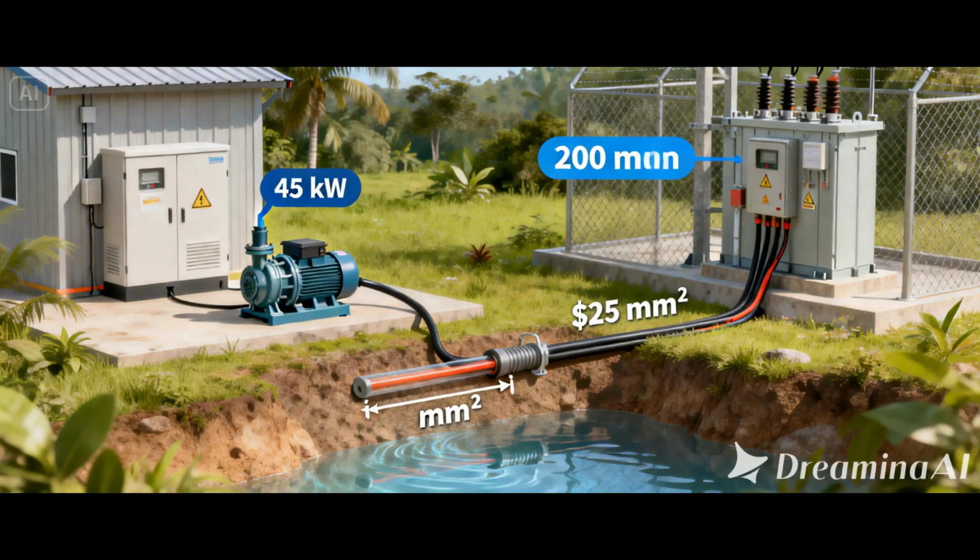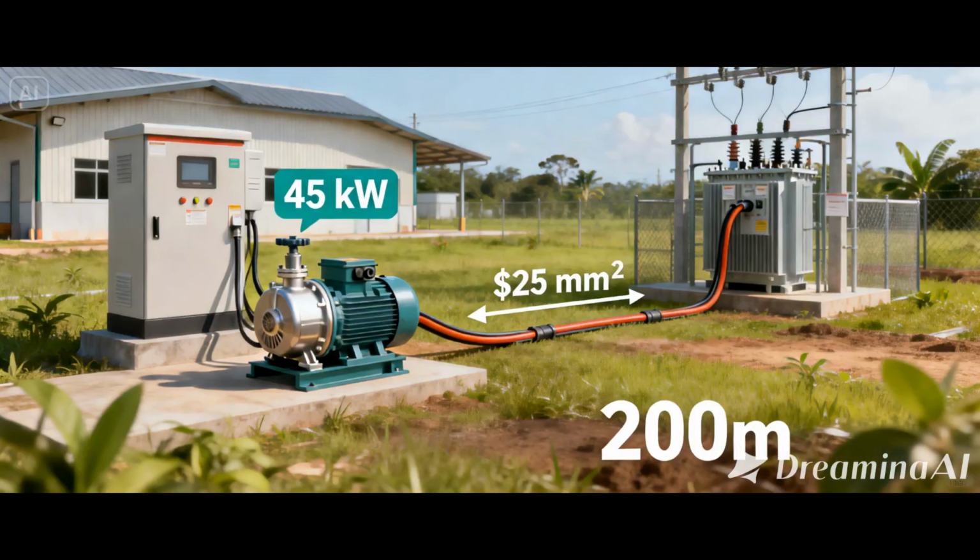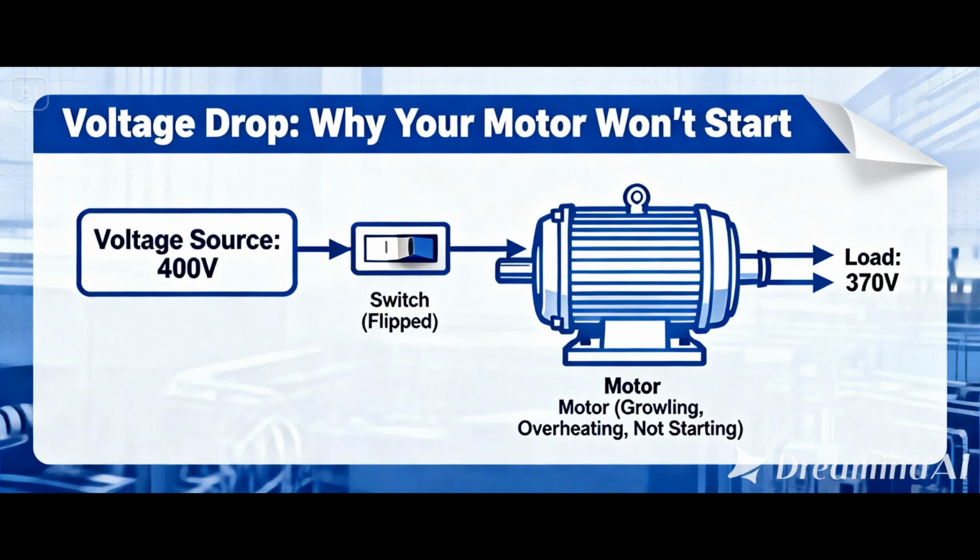If you're an electrical engineering student or a junior consultant, you've likely faced the classic power puzzle. Sizing a 3-phase cable for a long industrial run. Imagine this scenario. A 45 kilowatts water pump at a remote facility is connected to a substation 200 meters away. You do the math, select a 25 square millimeter cable, and install it.